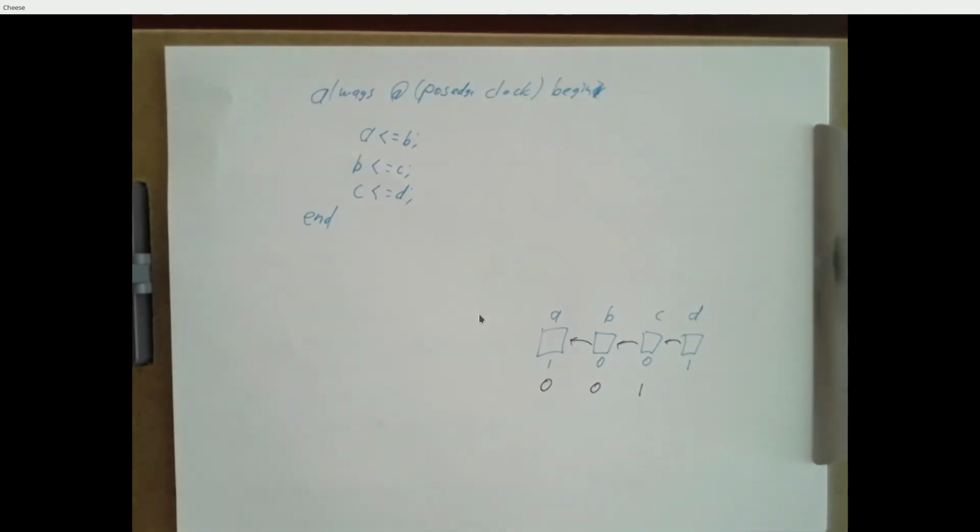And each time that this happens, there's some bit that falls off the edge, right? And that's usually the output of the shift register. And there's also an opening in the beginning, because you move things down. That's the input to the shift register. So you made a 2-bit version of this for your traffic light lab, right? It was a delay circuit is what we called it, but it was basically a shift register with 2 bits. So this is one way to implement a shift register.